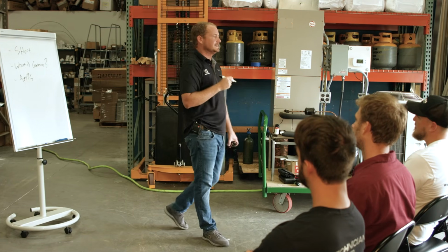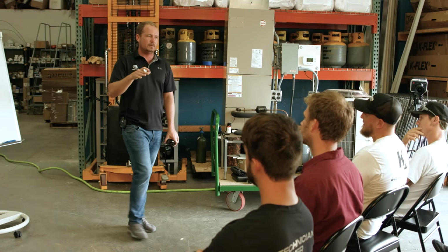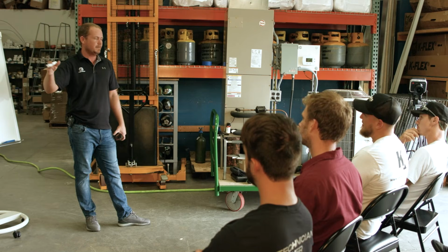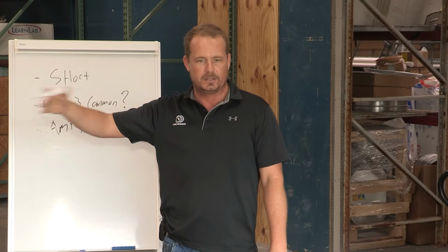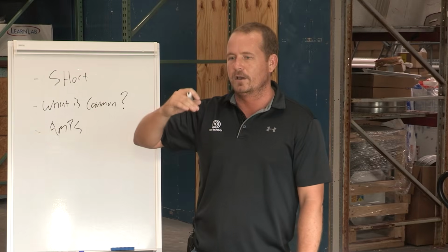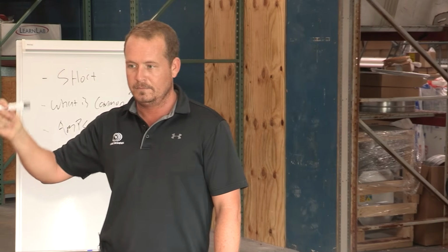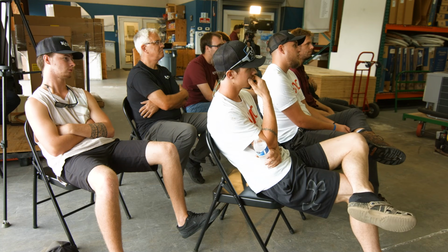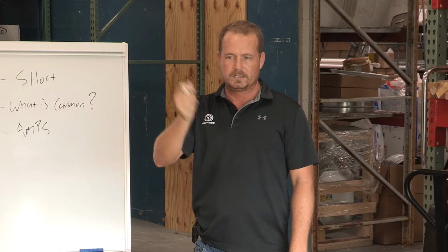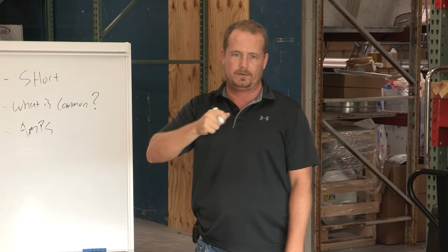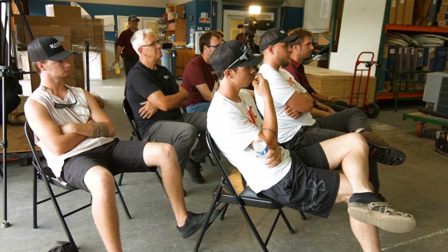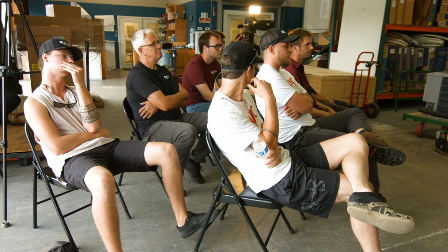In fact, if you were to run, say, 6 amps through a fuse, do you think it would blow right away? It would not. It would sit there for a while, and then eventually it would probably blow. But if you tried to run 100 amps through it, what would happen? Pop right away. And what happens if you take a low voltage wire, like your Y wire or your red wire, an energized conductor, and you touch it to ground? Pop, right? Instantaneously, the fuse blows. If you've done it, you get a nice little arc, and the fuse blows.